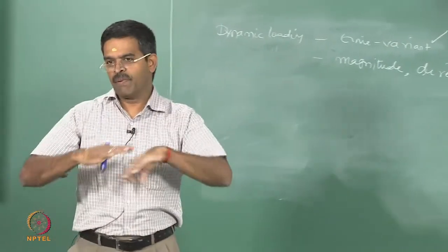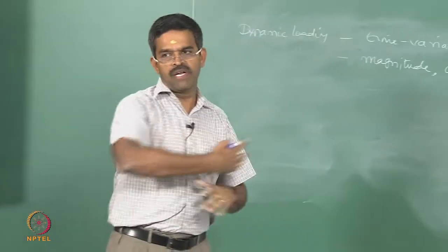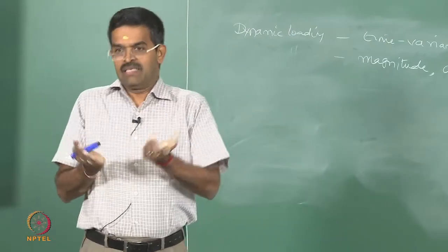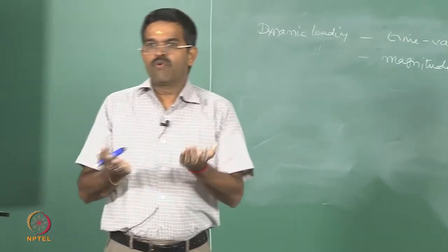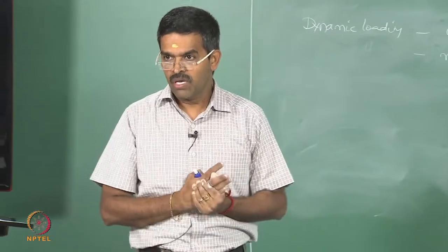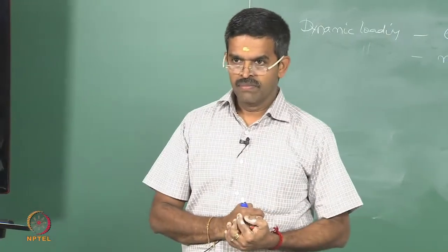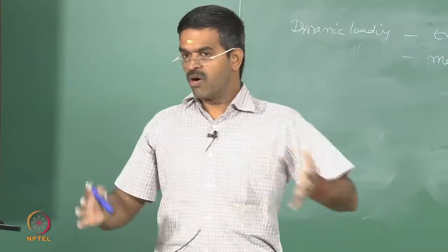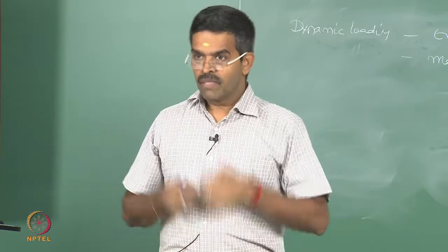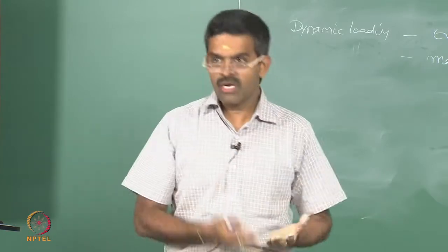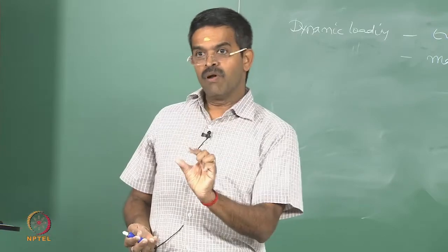For example, I have a paper, which has a lot of degrees of freedom to move, and the paper is massless. So I do not generate inertia force, because m x double dot is the inertia force. I do not have mass, so I do not have to do dynamic analysis on a paper. Alternatively, I have a huge box which is very massive, but the box does not move. Still I do not have to do dynamic analysis, because x double dot is very low.